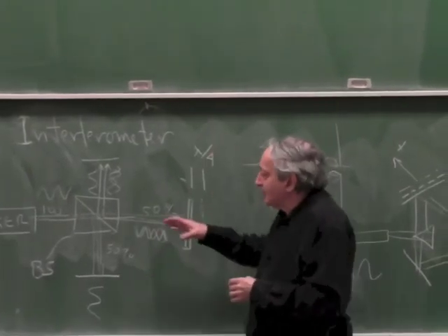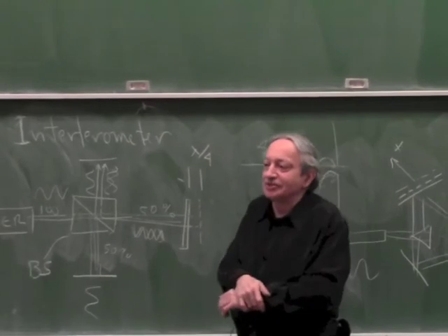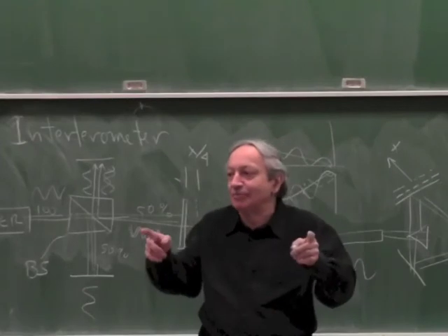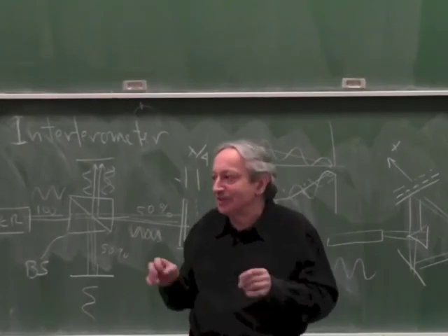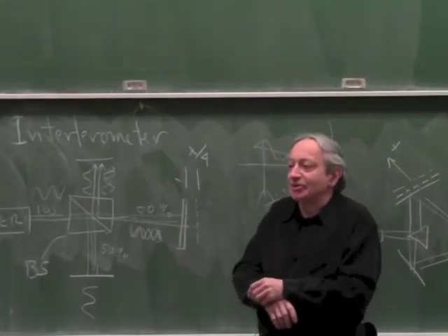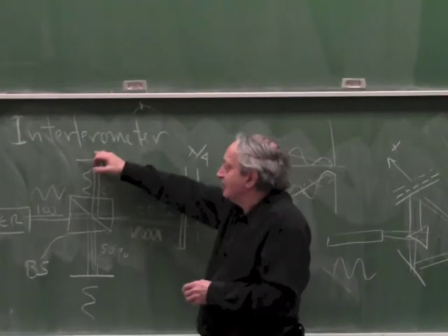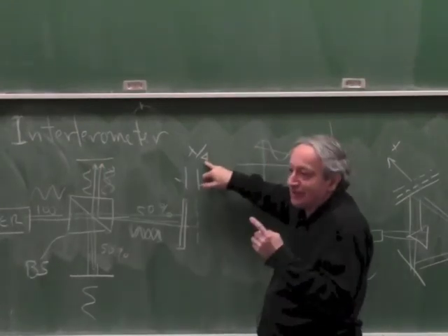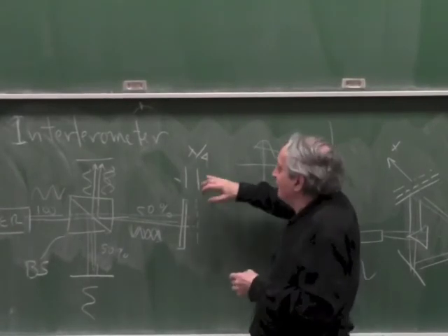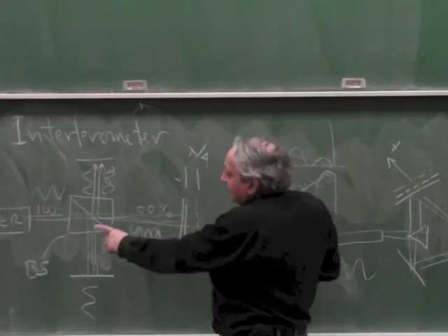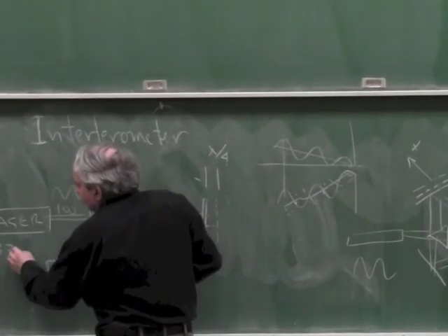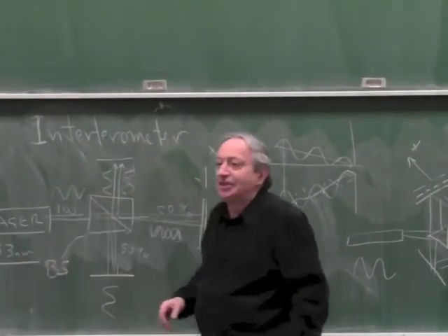So anyway, he realized that this is a very, very good measuring instrument, and he got interested in metrology, into standards. Say if you have all kinds of standard bars, you want to compare them, standard meter, standard yard. So he started applying it for very precise measurements, because not only does it switch from dark to light with a quarter of a wavelength of light, you can interpolate between, right? Today this is typically done with 633 nanometer, because that's the wavelength of the helium neon laser.